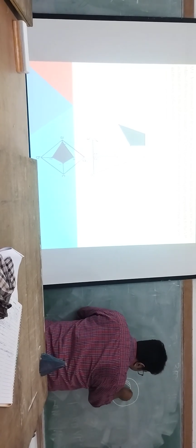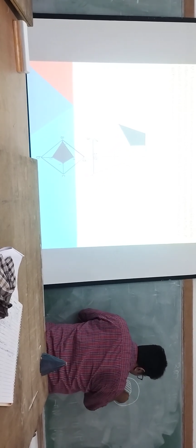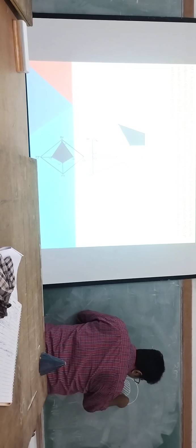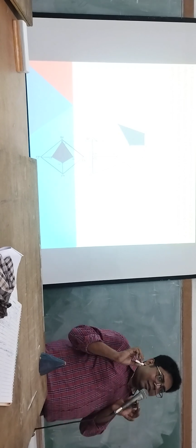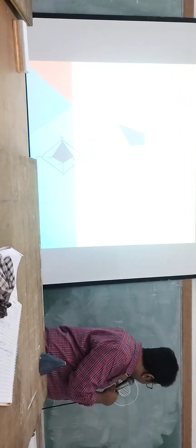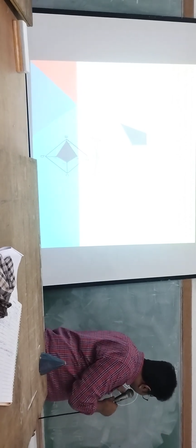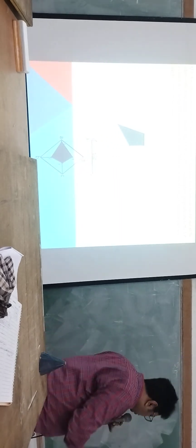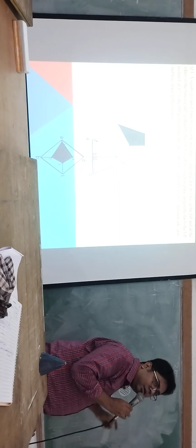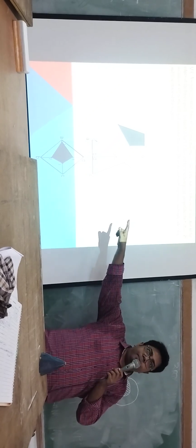So you take 45 degree line with same spacing, free hand. Okay, with scale freehand sketching. Means that you need not to measure the distance, actually just arbitrarily you will draw the same line, parallel lines all, and try to make it more 45 degree. So this is actually called the hatch lines or section lines. So this is actually your front view, this is top view, and that is the true shape.